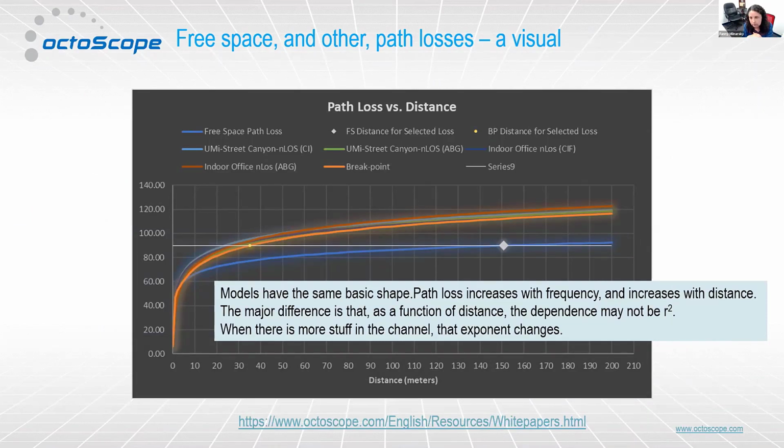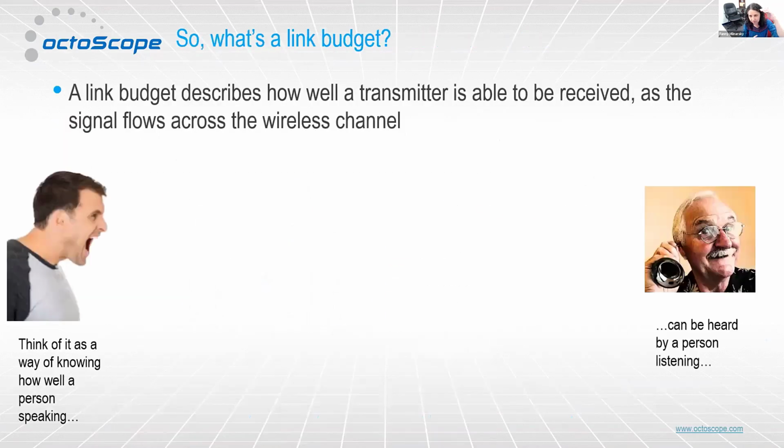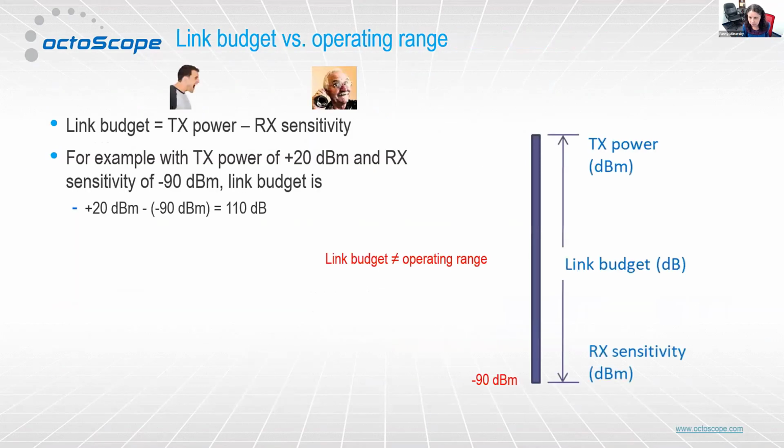When you're testing, for example, the full range of your link, the important thing is that you can get, like Lee was showing, the link budget from saturation to disconnection to below your sensitivity. If you have that full range in the test bed, you can effectively test indoor and outdoor links. That's true in the Octobox. Our attenuators have 90 dB of range, and they will disconnect even LTE, which is the most challenging to disconnect at lower frequencies. So yes, it's usable for indoor and outdoor links.